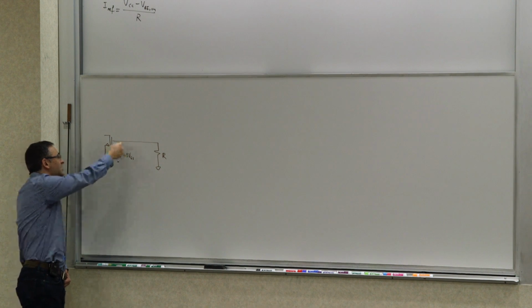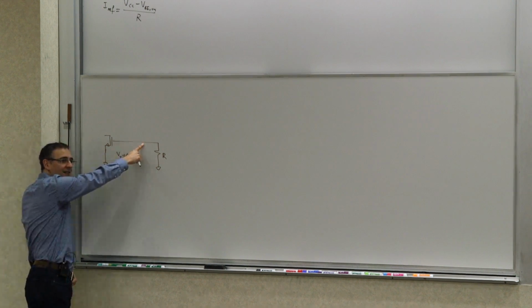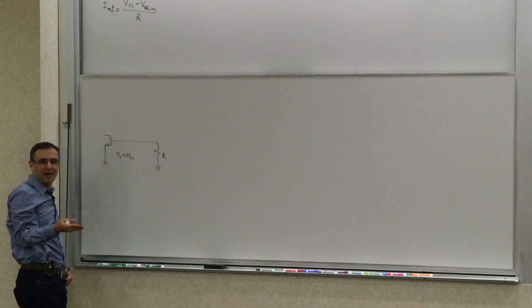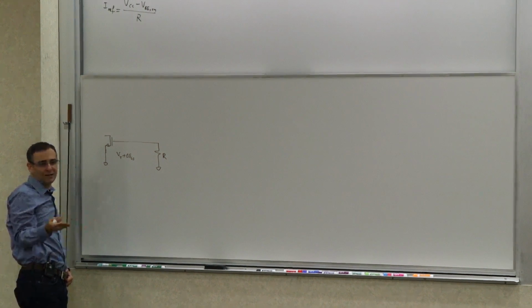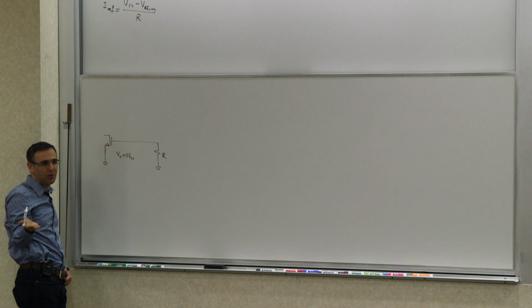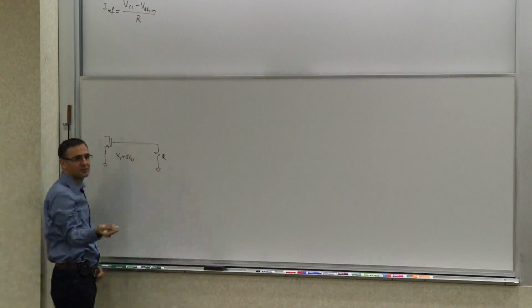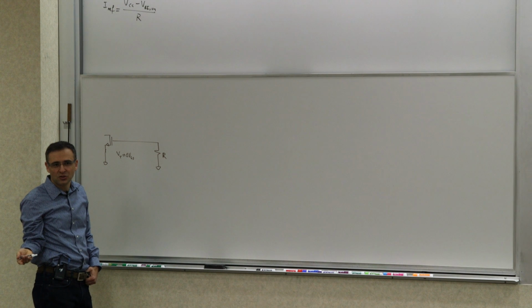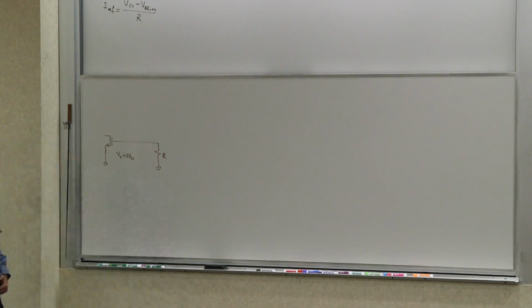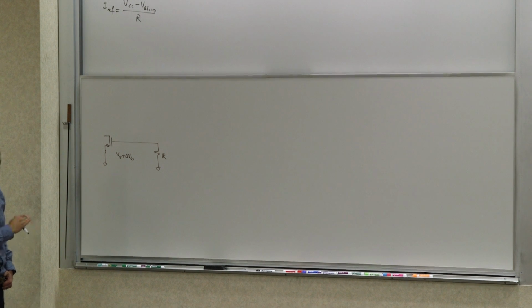Yeah, the transistor will turn off because this gate is shorted to ground through this resistor. So eventually it will discharge to ground. You will go below VT, unless you have a depletion mode MOSFET, in which case it will still be on. But if it's an enhancement mode MOSFET, in other words, if VT is positive, it's going to turn off. So nothing's going to happen. So this by itself doesn't work. But it doesn't mean that we can't make a modification to this to make it work.